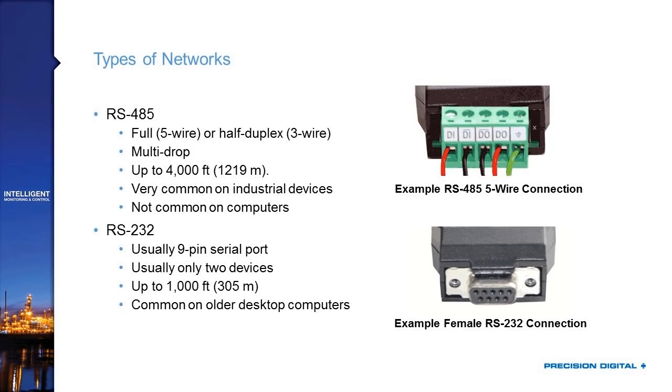Now, the big problem with RS-485 is that it's not a common computer-based protocol. If your goal is to eventually bring this RS-485 into some desktop computer in the control room, or you want to be able to use Modbus for device programming in the field and you want to connect it up to your laptop, RS-485 isn't very convenient for that. It's great for field wiring because it's just, in most cases, running 3 wires around to all your different devices. But getting it into a computer is going to require some other kind of adapter or input card.